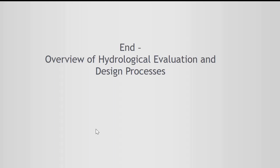Then we go to Flowchart 2, the process 2, the inflow design flood process to determine the hydrology for design. We determine consequences, fit those into one of 4 hydrologic hazard categories, get an inflow design flood criteria, model that inflow design flood, and that is the basis for your design.